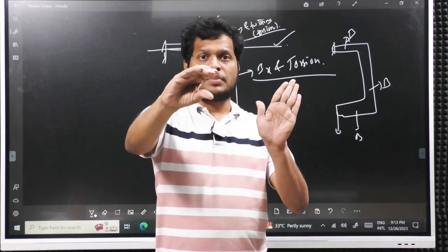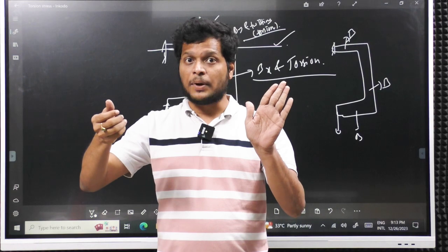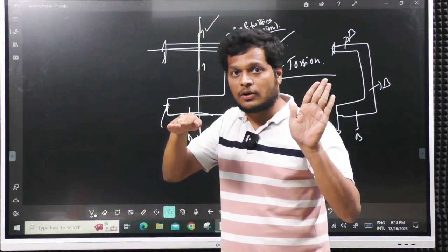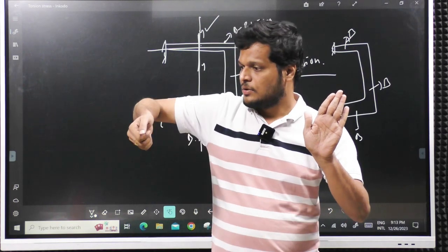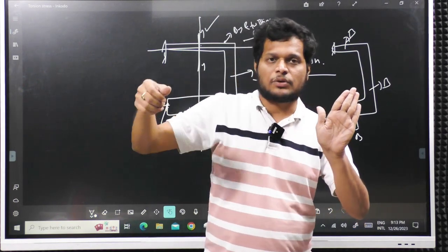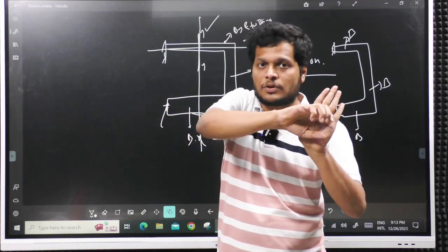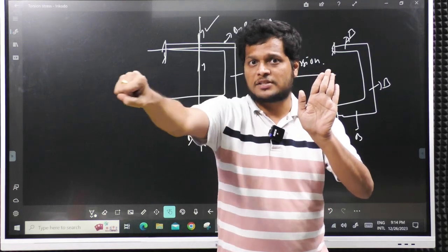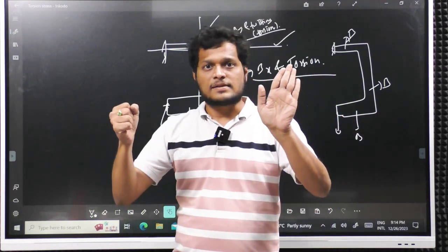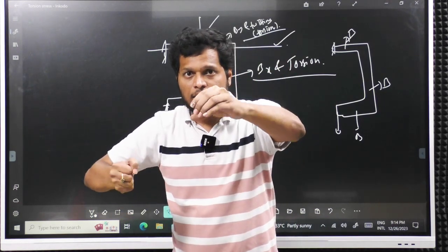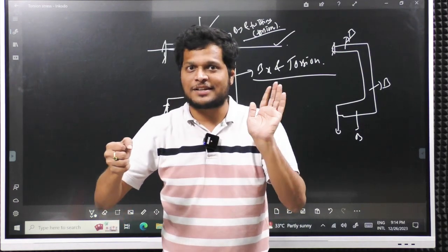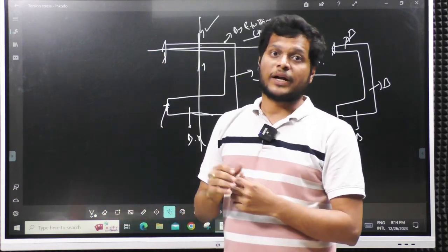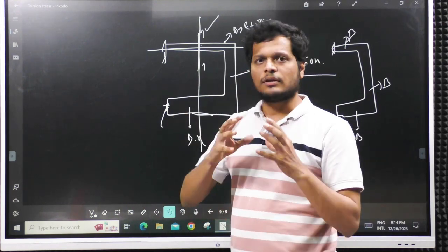So, imagine there is a beam like this. Okay. So, if I apply the load out of the plane, so this is the plane, right, out of the plane load comes like this, within the load plane comes like this, because I assume this as plane. So, if within the plane I apply, everything bends without twist, you can imagine that, right, along the plane. So, everything gets bent, one will be in x, one will be in y, but it simply bends. So, there is a fixed beam here, I attached a rod, load within the plane. Now, if I apply the same load out of the plane, this will bend, this will twist, you can imagine, right. So, by changing the load direction, some will be in bending, some will be in twisting. So, it is very difficult for you to identify which is in bending and which is in twisting. So, using this rule, it gets simplified.